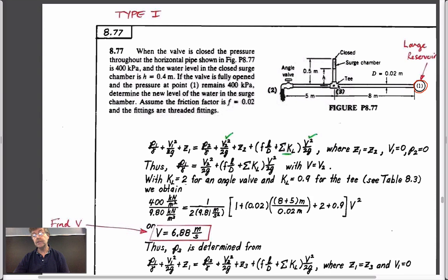And so what it might want to do is to carry on, not by going this way, but by diverting up this way against an air cushion in the top of this. And so I don't know whether it's a common fitting in a pipe network, but it's certainly a common fitting in hydroelectric plants where you have a reservoir, penstock that feeds the turbine holes. When you shut the gates of the turbine holes, you don't want all that momentum knocking those gates off, just like we saw in the Russian television movie maybe 8 weeks ago.